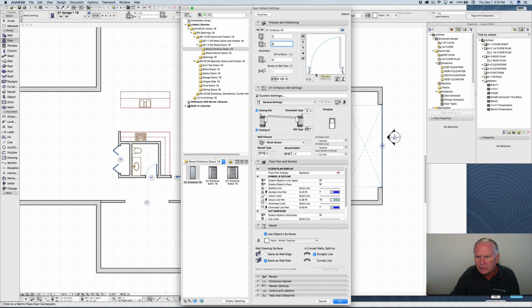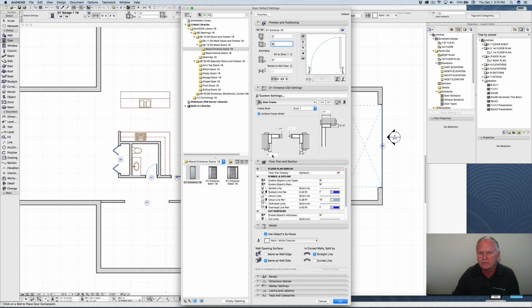That gives us a door thickness and a jamb. And actually, those jambs are a little fat for me. So let me show you how we can change those. We're going to click down here and go to door frame, and we have a door frame right now. It's 2 inches, probably more typical of being 3/4 of an inch. And type that in, and that'll put that in to this side and to the head piece as well. And just as long as we're here, we'll make one other change to the door. This is the frame style. You just see a basic jamb there. Since it's an exterior door, it'd probably be rabbeted. So we want to take style 3 and give ourselves a rabbeted, and then let's make that an inch.